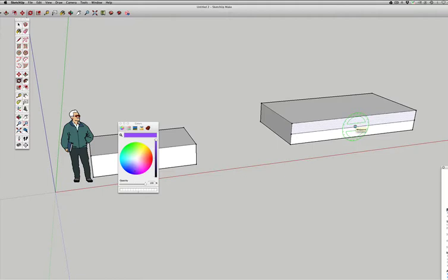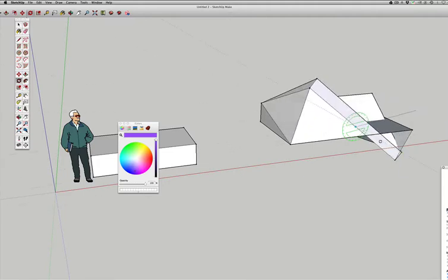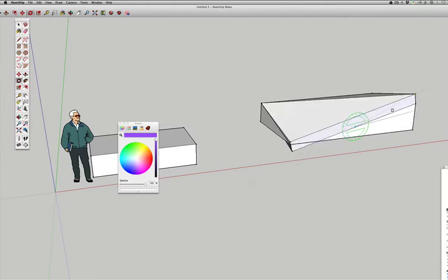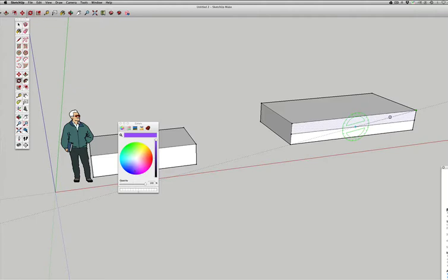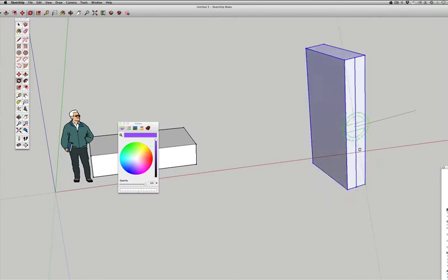All right, so I'm right at the midpoint there. I'm clicking there, and then I'm going to go right over to that endpoint. They're green. Now when I twist it, see? That's just twisting the front face of this. Now, if I do it with space, now I've got the whole thing. Hit Q again. I'm going to wait till I get to the midpoint, because that's light blue. I'm going to go on that endpoint, click on it. Now I can turn the whole thing over like that.